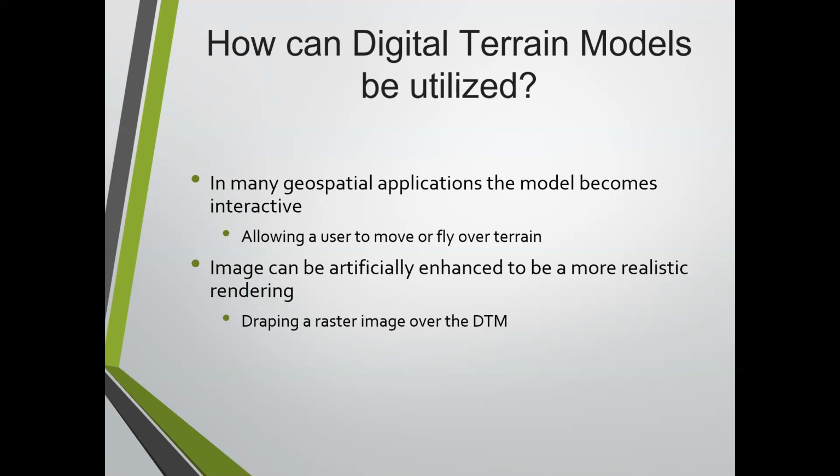And again, you think of it as just like a sheet that you lay on it, and that sheet has the printed information, and it stretches the photo or whatever texture you're using to fit on it, like that image of Mount Everest we looked at in the very beginning. So a lot of times you'll take realistic satellite imaging and you can drape it. I don't know if anybody has ever done that in Civil 3D, but Civil 3D has a drape routine that you can use. So you can take a raster image and lay it on top of your surface.